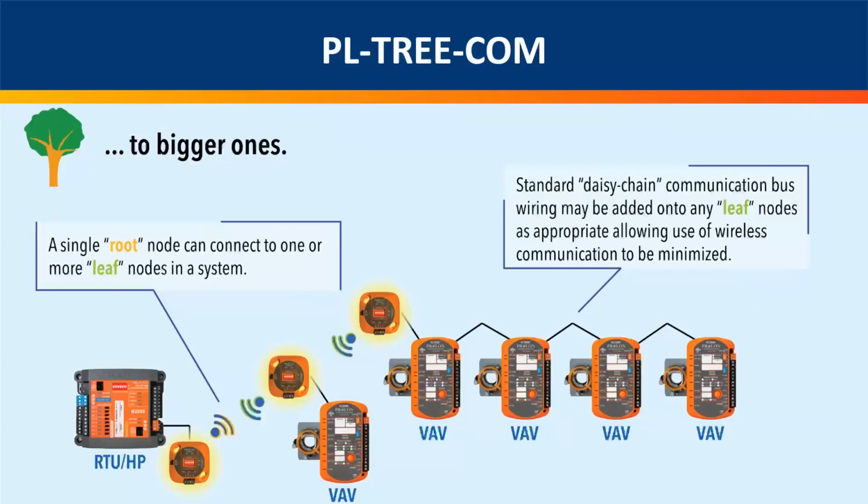If you turn on dip switch 1 and 2, 1 plus 2 is 3, that's address 3. One of your TreeComms on channel 3 is going to need to have dip switch 8 on. He's going to be the root. Everyone else will be leafs. And they can all talk together.